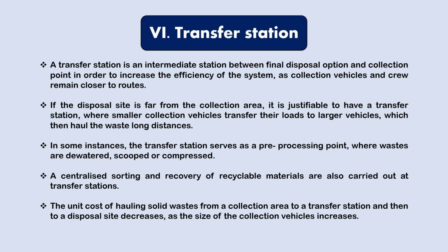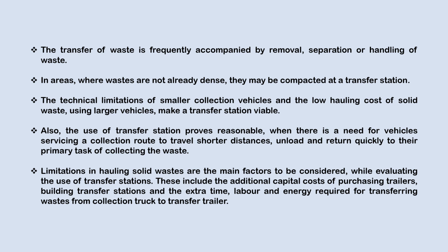So the transfer station basically serves as a pre-processing point where wastes are scooped and compressed, and the unit cost of hauling solid waste from a collection area to a transfer station and then to the disposal site actually decreases if we have a transfer station in between these two sites, disposal and collection sites.